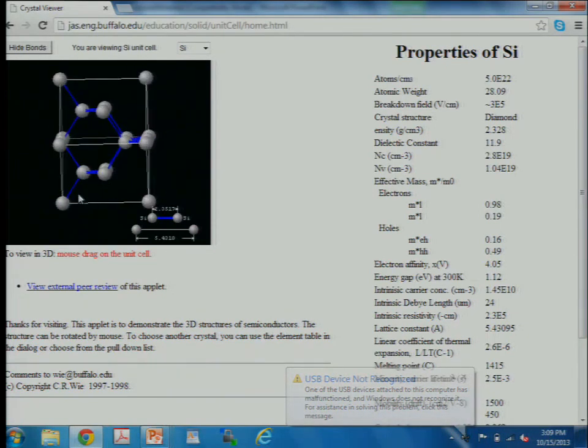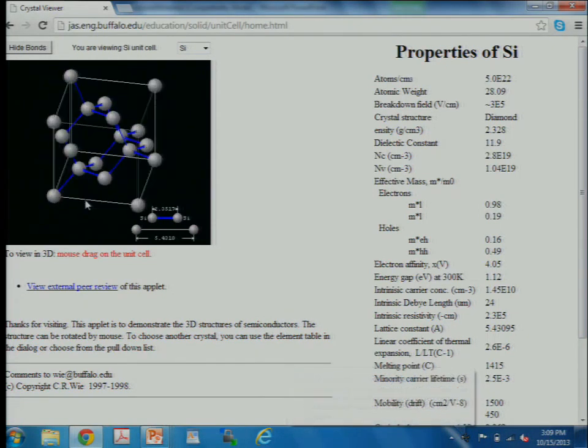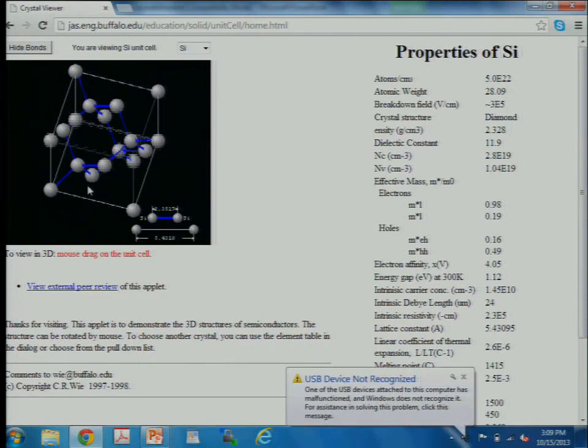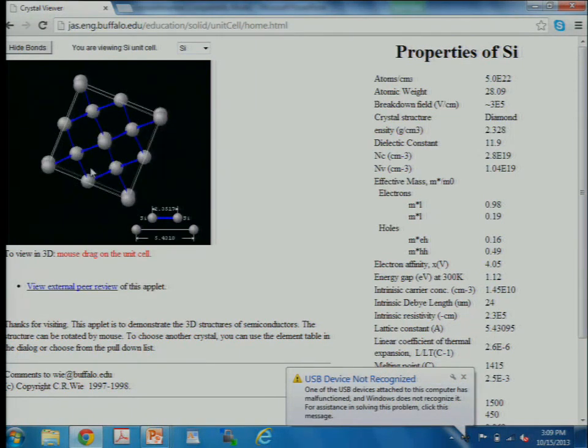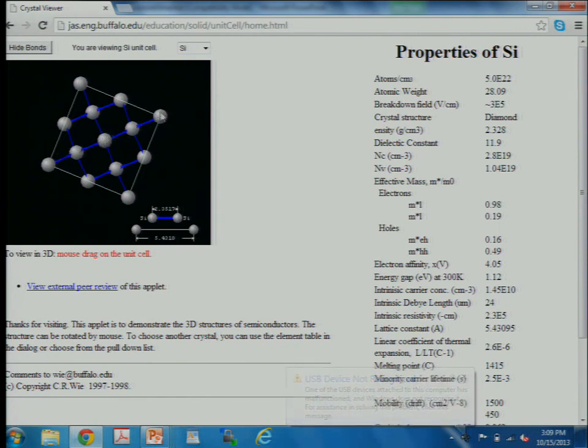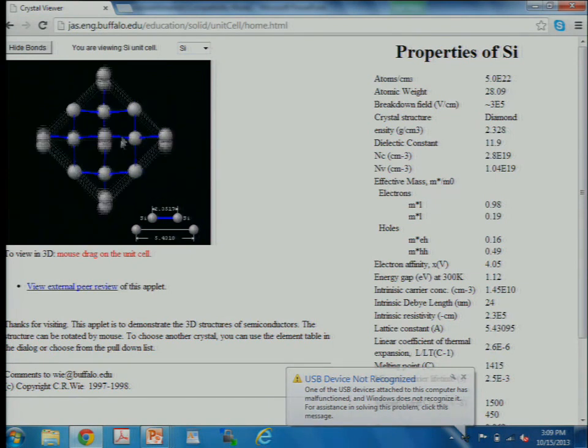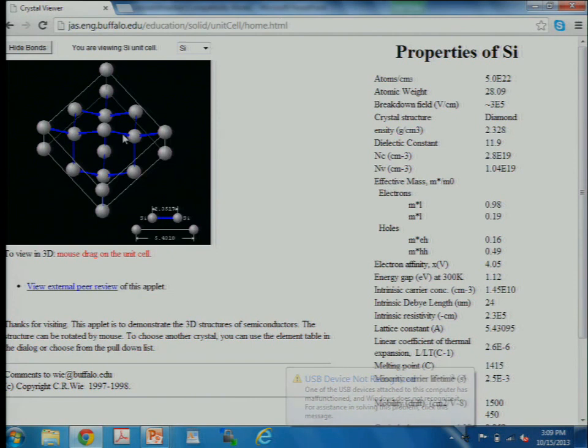Do you remember? Okay, so let's look, for example, at a 110 direction. Maybe it's hard to show. But okay, see these bonds over here? They're lined up along a 110 direction. Hopefully you can imagine that. Okay, so if this was the surface, like let's say all the atoms on this side over here are removed, and you have a plane of silicon atoms here, a 110 surface. So clearly there will be a couple of dangling bonds, but the rest of the bonds that are holding the silicon in place are to the side.